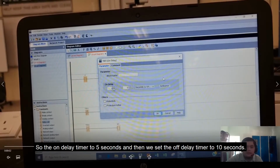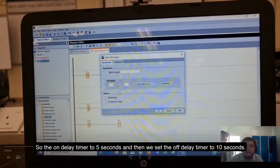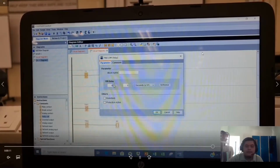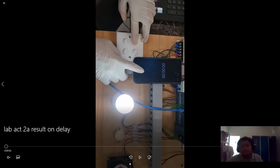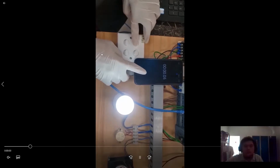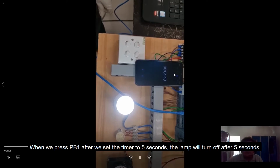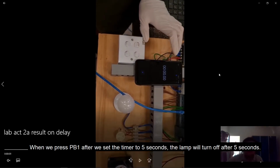We set the timer for on delay to 5 seconds and the timer for off delay to 10 seconds. This is the result for lab activity 2A, which is on delay for the normally closed contact. When we play this video and press push button 1, we set the timer to 5, then the lamp will immediately turn off.